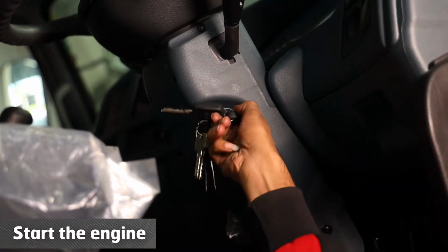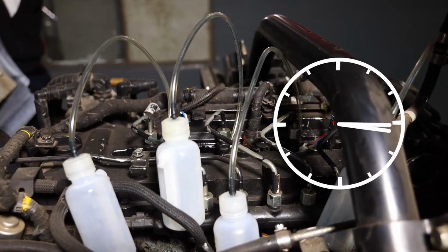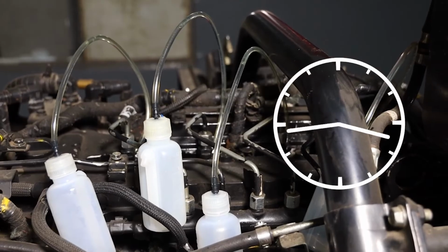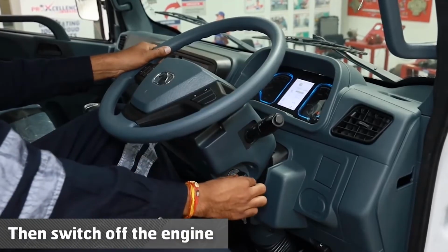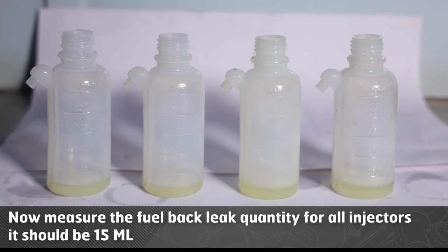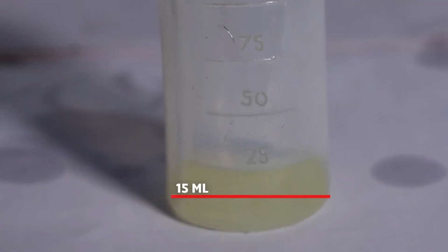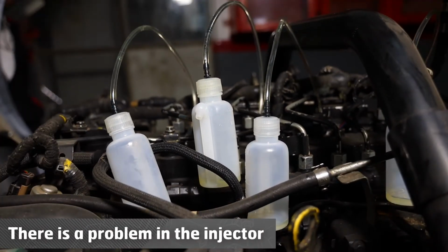Start the engine and keep it at idling RPM for 2 minutes. And then switch off the engine. Now measure the fuel back leak quantity for all injectors. It should be 15 ml. If injector back leak fuel quantity is more than 15 ml, it means there is a problem in the injector.